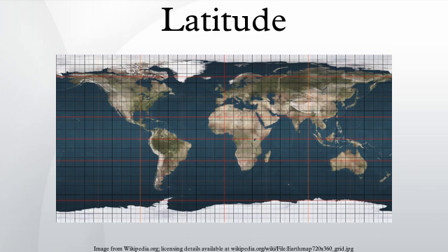Reduced latitude. The reduced or parametric latitude, β, is defined by the radius drawn from the center of the ellipsoid to that point Q on the surrounding sphere, which is the projection parallel to the Earth's axis of a point P on the ellipsoid at latitude φ. It was introduced by Legendre and Bessel, who solved problems for geodesics on the ellipsoid by transforming them to an equivalent problem for spherical geodesics by using this smaller latitude. Bessel's notation is also used in the current literature. The reduced latitude is related to the geodetic latitude by the following.